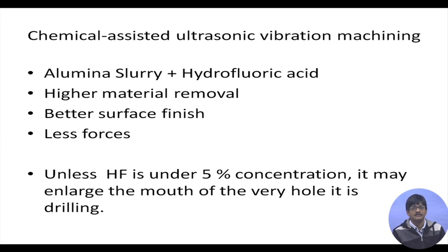One is that the material removal rate is not very high, and the surface roughness is also not very good, because it directly corresponds to the average grit size.